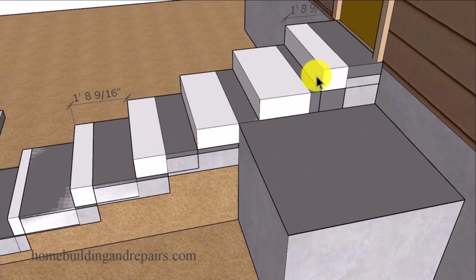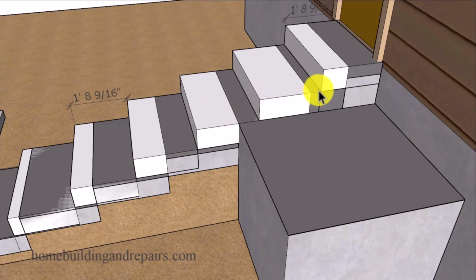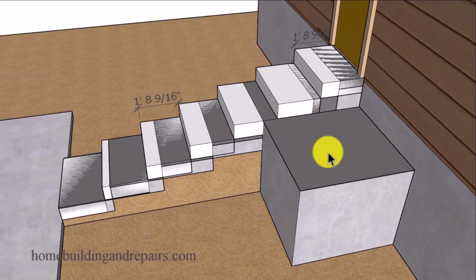Now, another problem you're going to have with this stairway is that you need 3 feet somewhere. Either this step right here needs to be 3 feet long, or this step here would need to be 3 foot. We need 3 foot in length to provide us with a step down or an even transfer to the landing here. However, you could always put a handrail on this side or a guardrail to prevent people from walking over to this side here, and then maybe put some plants on top of it or repurpose it somehow to make something like this work.